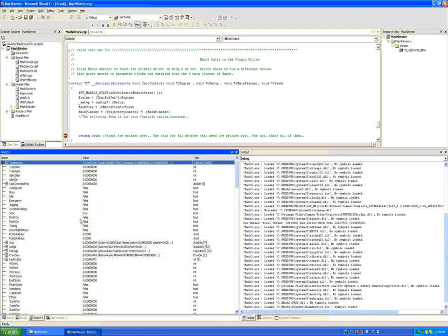Port 1 and 2 on, you can see both set to false at the moment. This init control is set before Mach3 has fully started up. So port 1 and 2 are both off because Mach3 does not know yet that they're turned on. It has not done its primary initializations. So really this init control routine is not a good place for you to change variables within Mach3. You should wait until the configuration or in your update loop to change any of these variables. At that point, these variables would then be instantiated.